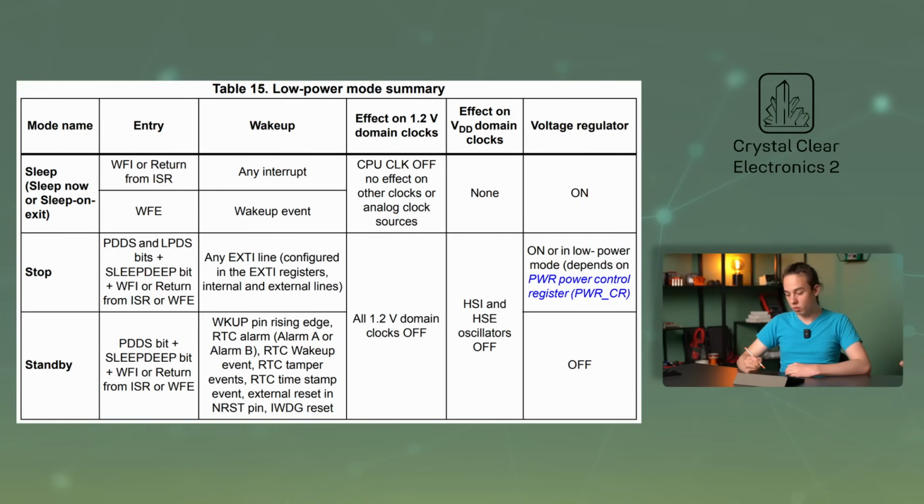One low consumption mode is the sleep mode. Using the sleep mode only shuts down the processor clock, but the peripherals continue to run at the preset clock frequency. This way, they remain fully functional and are able to generate interrupts. From this state, any configured interrupt will cause the system to enter normal mode, which will occur almost immediately.